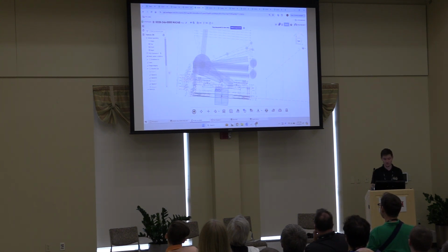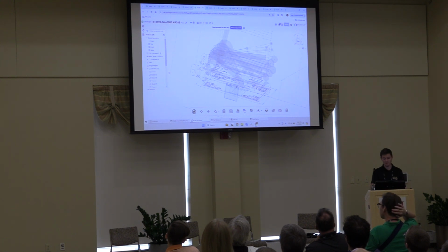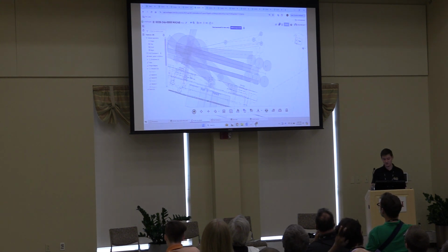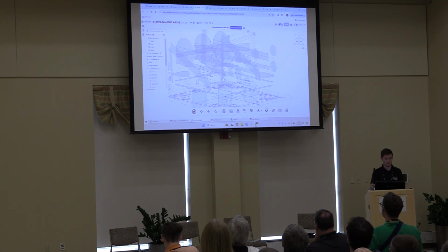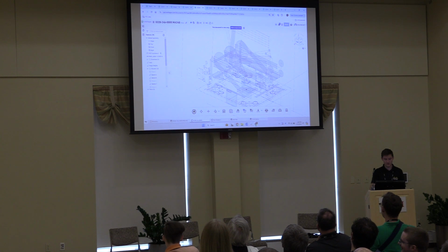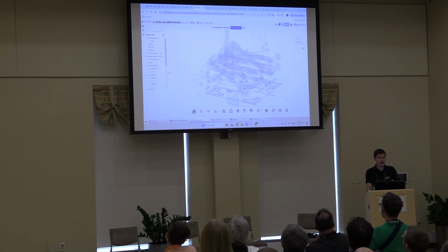They are referencing the origin as the floor. And then each of these sketches is just an offset plane and another sketch, an offset plane and another sketch, that is capturing the major locations from their prototypes: bearing locations, flywheel locations, where the tubes need to be, where the pivots are. So it is intimidating. I found it very intimidating. But especially if you look at how other teams have done it, it does become pretty clear how to do it and what is most important.